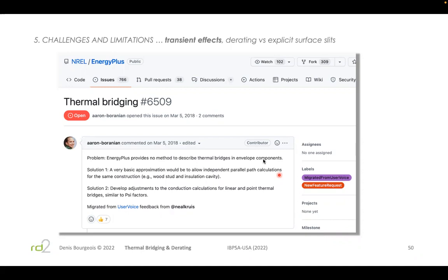My understanding, okay, so the other question was, in my testing, I found thickness and conductivity adjustments do lead to different results when the insulation layer has meaningful thermal mass. I do agree, such as in a timber frame wall, and I was wondering if there was evidence supporting one approach over the other. We don't have a lot of sensitivity analysis there.